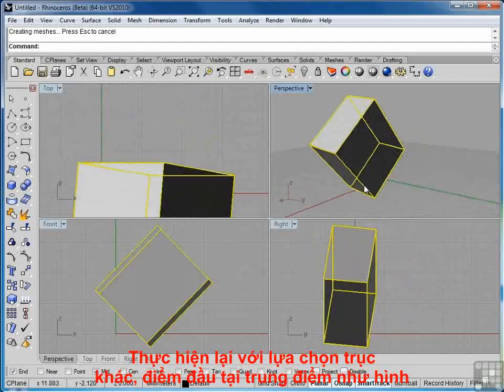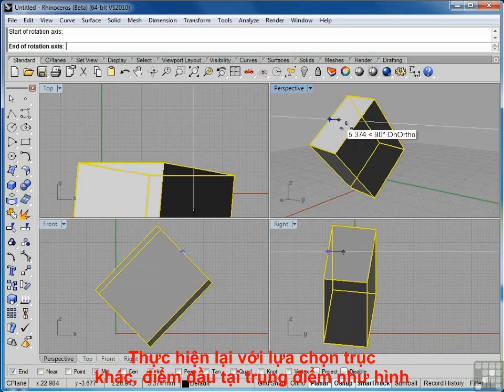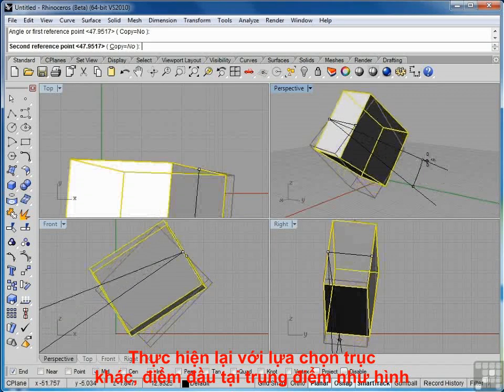So we're no longer rotating right around the construction plane anymore. Let me apply that command again. We'll do a little bit different. This time I'll use a midpoint to confine my rotation axes. So now it's as if there's an axle across this point.